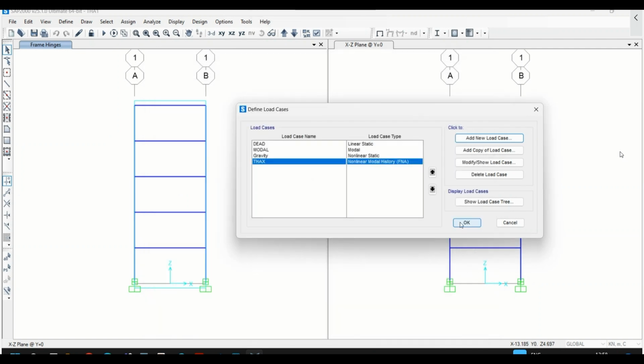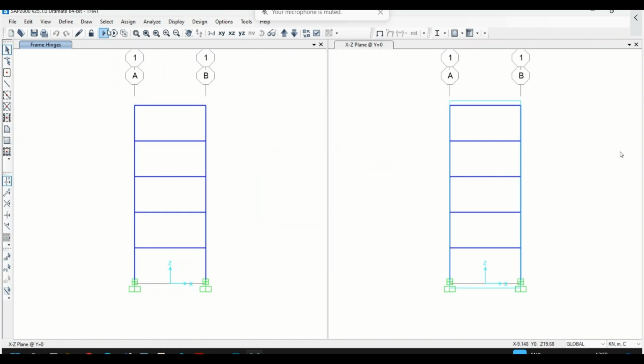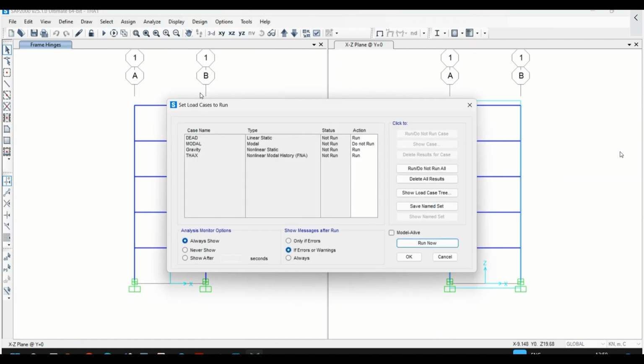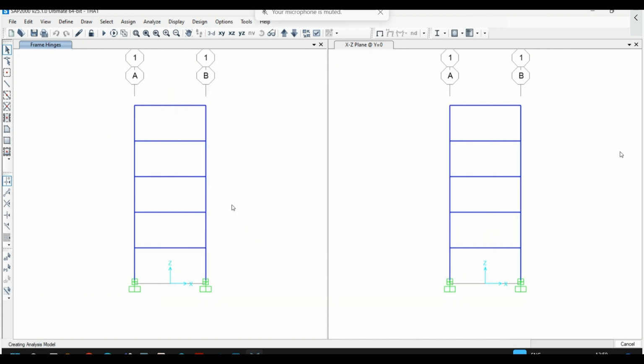and so the program is capable of doing both model time history analysis as well as direct integration, like Newmark beta, Wilson theta method, etc., using step-by-step direct integration. Let's go with this and let's run the analysis. Don't need the gravity for now. Let's go with.